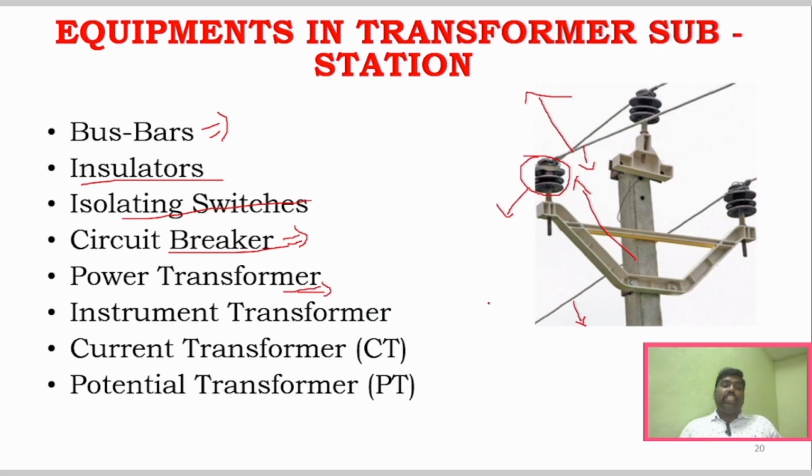And this is very important, instrument transformer. What is instrument transformer? What is the need for it? We know that the power lines in the substations are at high power, of higher voltages, whereas the instruments or the equipments which we use to measure will work at low voltages. So these instruments, when mounted in these power lines, will not be able to work fine. So what we will do is, normally we will use instrument transformer, which converts this higher voltage to a lower voltage for these instruments for measuring purpose or for any other devices. So that conversion will be taken by this instrument transformer.